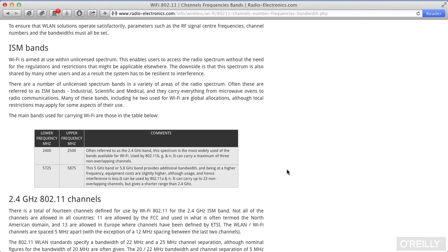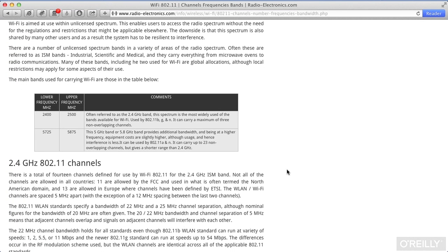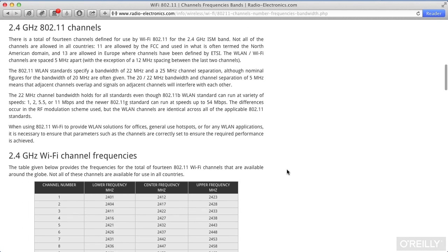One of the issues that you'll see sometimes is if you've got, say, a cordless phone that's acting up that's really old, or a microwave oven that's really old. You've got some of these older electronics that are operating somewhere near that same frequency range that your 802.11 Wi-Fi systems are using. You may start to see spikes into that same frequency range that 802.11 is using, and you could end up seeing degraded signals as a result. So there are a lot of consumer electronics that are operating in that 2.4 gigahertz range.